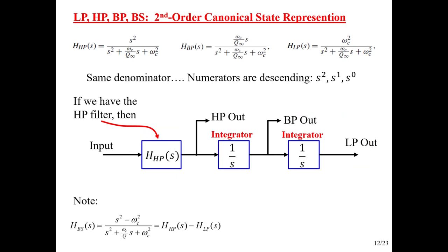And I should also point out, remember, here's where we get the band stop. The band stop we saw back in a couple note sets ago, that the numerator was S squared minus omega C squared. Remember, that put zeros, conjugate zeros, right on the J omega axis. So boom, taking the response down to 0 at some particular frequency. That's what made it a band stop.